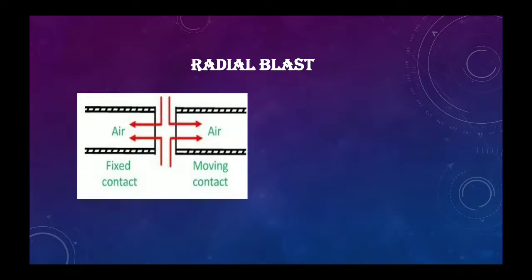This is the fixed contact, and this is the moving contact, and the air is charged radially from this side, and from this side, and this side, and it extinguishes the ionized gas or ionized medium between the fixed contact and moving contact, and hence the arc is extinguished.